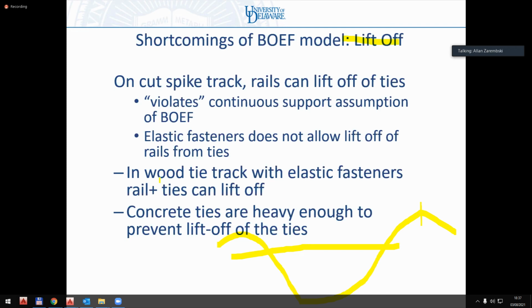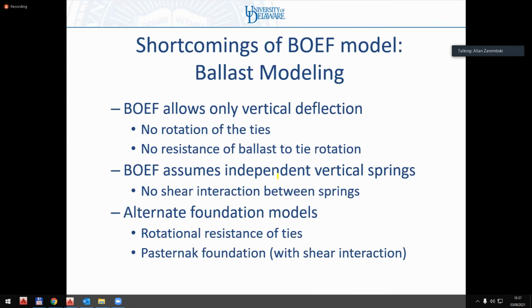On wood sleepers, you always get an uplift because the lift-up force of the beam on elastic foundation is heavier than the weight of the wood sleeper, but not as strong as a concrete sleeper. So that's a shortcoming, but it's an approximation, and the approximations are still pretty valid.